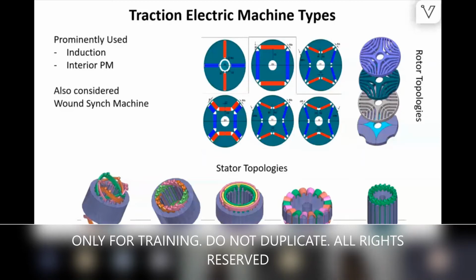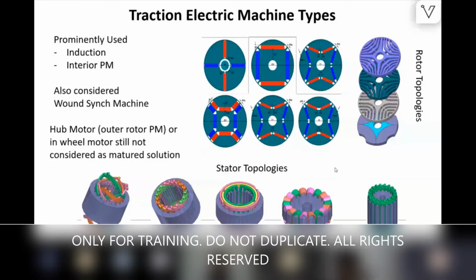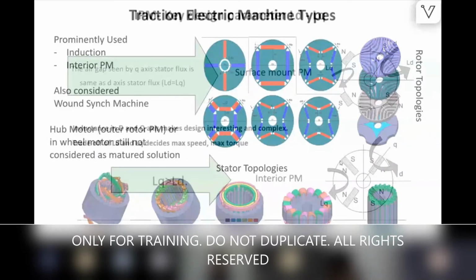It's a very critical element that we have to look at, and when we deep dive, we'll have to see what harmonics the inverter brings in, what kind of reduction is possible there, and what kind of reduction is possible in the machine. So here, depending on the machine winding strategy, we can really decide about the harmonics.